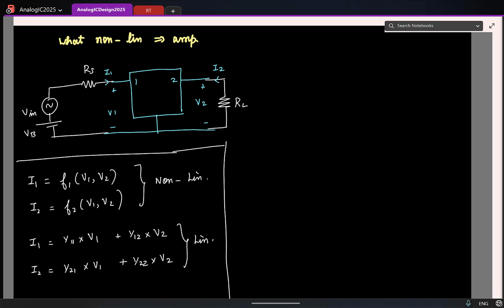So if I look at all the voltages, V1 will have an operating point voltage, I'll call it V1O, plus the small signal voltage delta V1. Because now in my circuit I have both a DC part as well as a small signal that I want to amplify.